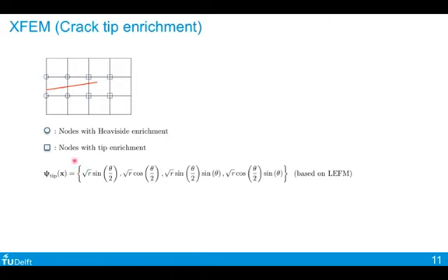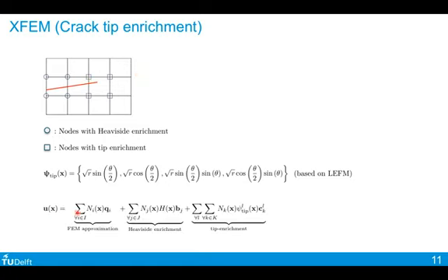They are composed of these basis functions. The idea is to make use of these basic analytical basis functions to enrich the interpolation space of a finite element near the crack tip, for instance, this element, so that the overall displacement interpolation within a certain element in X-FEM is composed of 3 parts.